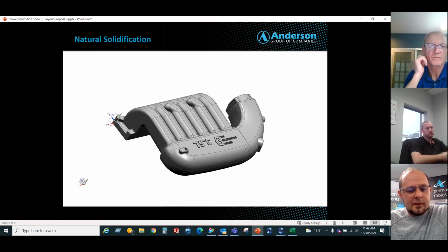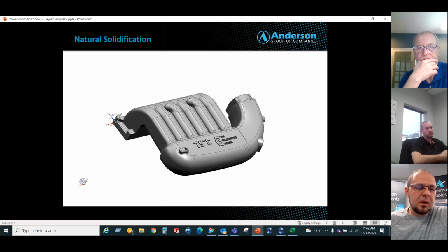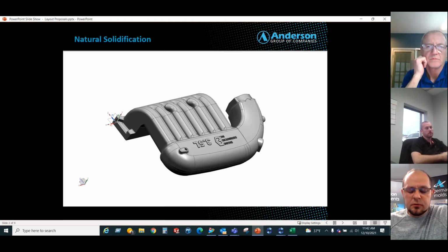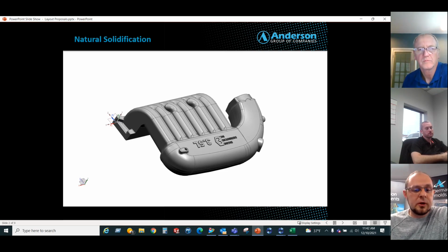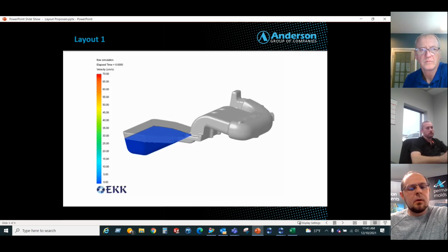And depending on the complexity of the casting, it takes quite a few tries sometimes to get it figured out. We start with design for manufacturing, which is usually done by Ben Flower, our engineering manager, where he analyzes the casting for backdraft issues, core package issues, how the partings are going to look, and things like that. And then we start laying it out.